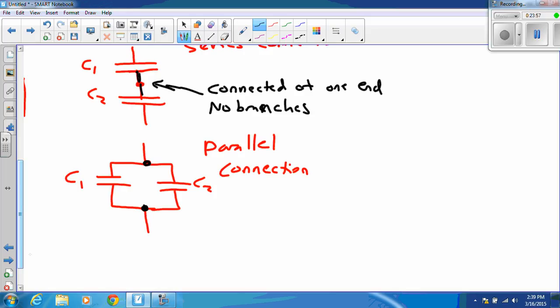And so Christmas lights in series, if one of them goes, what that does is it takes out the ability of current to flow through the whole strip, right? If they're in parallel, then each one is directly connected to the power. So if one goes, then the rest can still go. That's how your household lights are wired, or should be wired. If they're connected in series, there can be more problems than one. So you should have lights in parallel, so that if one light bulb goes, you replace that bulb, and that's it.